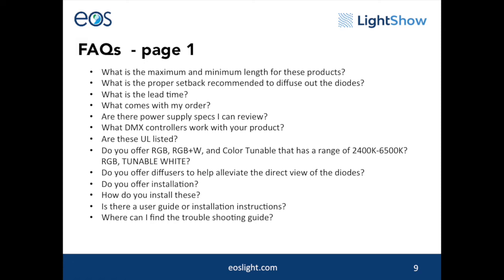How do you install these? Panels are shipped with the appropriate specified hardware. The 2 standard means of attachment include a shaped steel or aluminum channel, known as strut, or a steel or aluminum angle. Drawings provided with systems will detail the method of attachment. Is there a user guide or installation instructions? Drawings of the panels are provided with the purchase of a system. For larger projects and orders, we can coordinate with design teams in specifying the correct method of attachment.